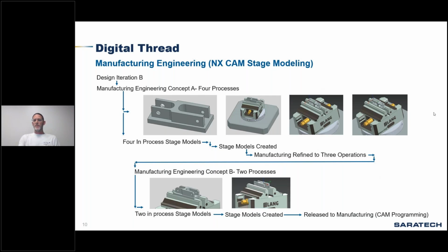So the process that we're talking about on the bottom left here, that's held in the vise. I could machine that part 100% without touching anything, without selecting the part, without doing anything. I would just utilize feature-based manufacturing, and then all of our operations are volumetric. I tell it that the vise is a check surface. I tell it what a clearance plane that I have, and then I just tell it to do it. It'll go stock to finished part, missing the vise.